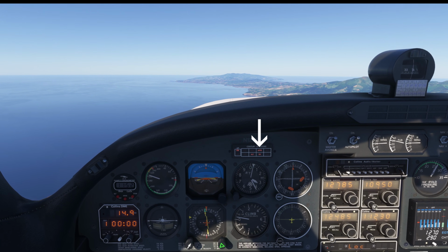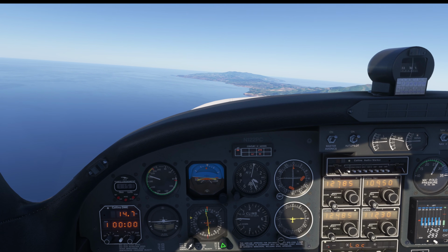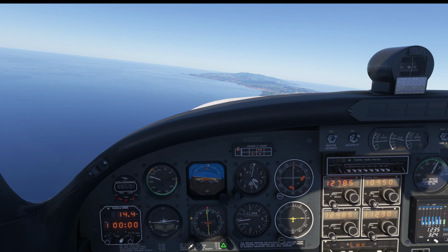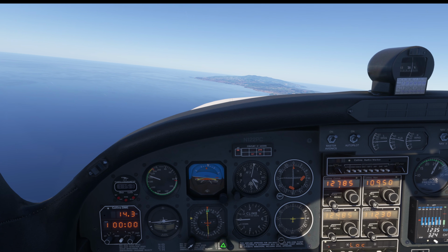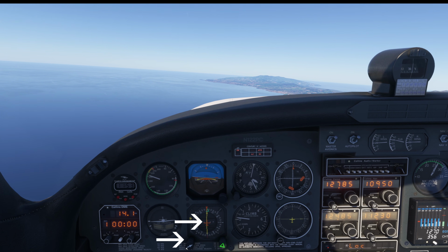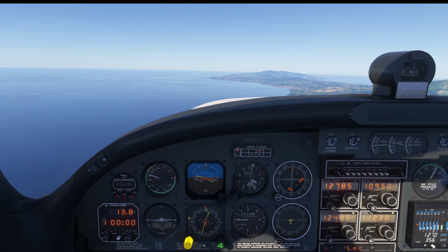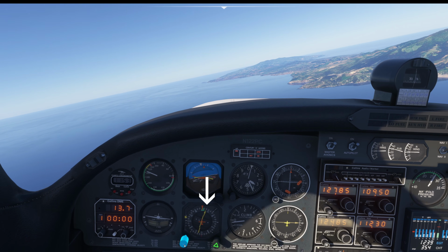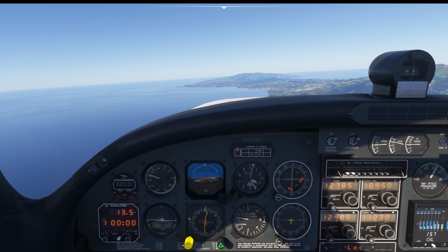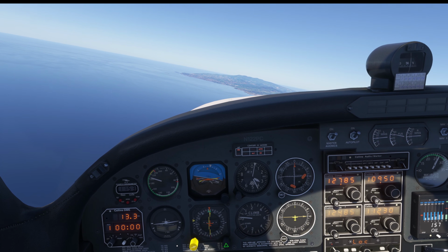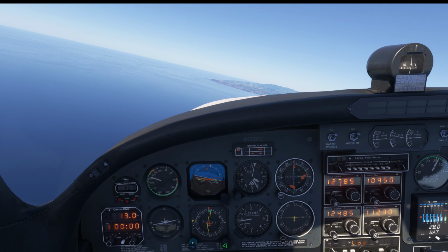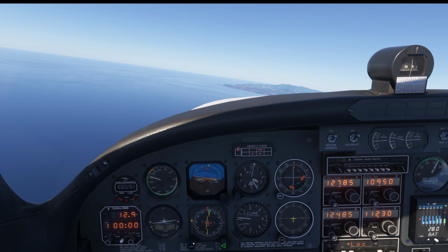The approach mode works exactly the same. The difference is that the autopilot has different gains to better track localizer signal, but it is still using course setting and CDI to fly the approach. That means you have to set the course arrow to ILS inbound course, or the ILS tracking will likely fail, because the autopilot will receive conflicting information about the intended course and deviation.